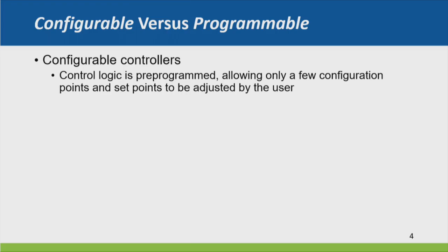So part of the genesis of this was this dichotomy between configurable and programmable controllers. When DDC first started, we started with configurable controllers. These are controllers where the logic is burned into it. For those that are used to Lon systems from a while back, they mostly followed this philosophy. We're just going to burn the sequence into the thing, and all you can do is configure it. You can change the CFM set points and other things, but you can't actually change the logic.